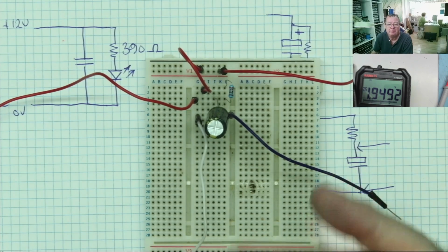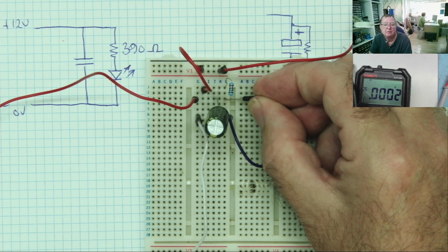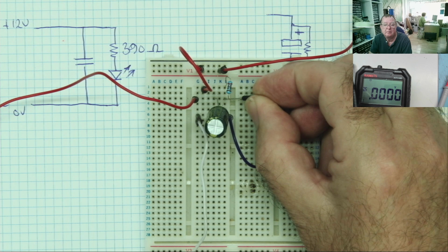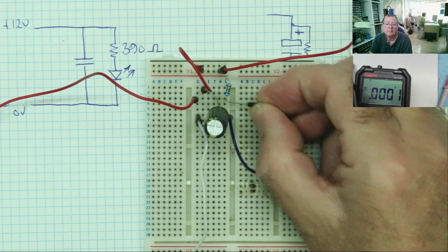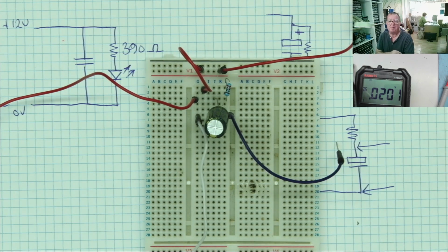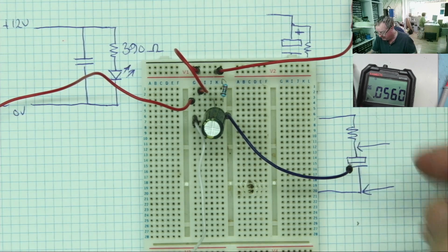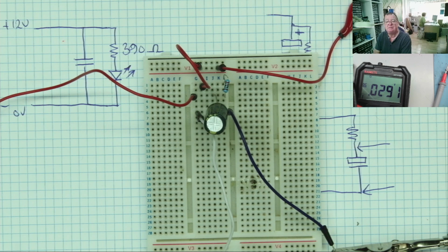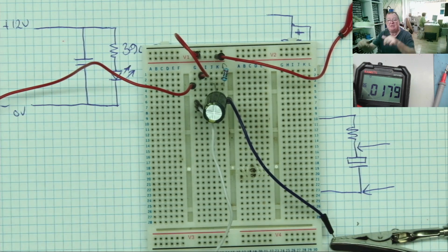Well, straight away, without connecting any power, we can see there's still some charge in our capacitor. So to get rid of that charge, I'm just going to short the capacitor out. And I've now discharged it. See the little bit of recovery I was telling you about? Wait a little bit longer. Once again. And you'll see our capacitor is pretty close to discharged now. It's got about 0.02 of a volt in it, 0.03, not very much. Okay, so let's now connect the power and see what happens to the voltage in our capacitor. And while I'm talking, by the way, you'll see that that is now discharged again. This is this kind of bounce back thing. Maybe we can talk about that in detail at some point. To me, it's just something that capacitors do, and I don't overly worry about it, okay? But if you want to talk about it, comments below, guys.